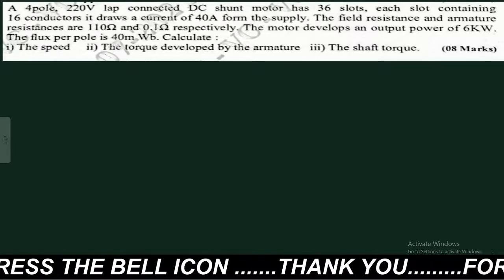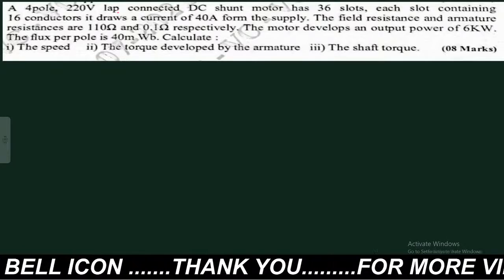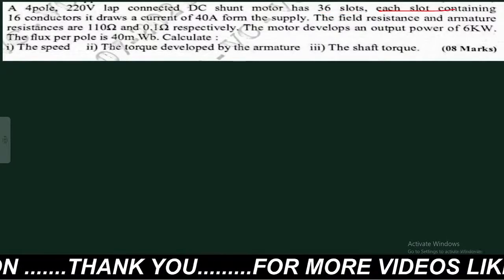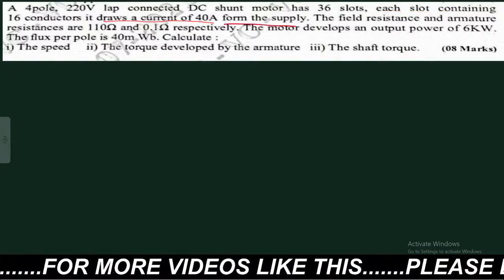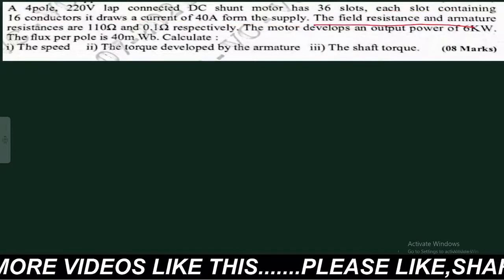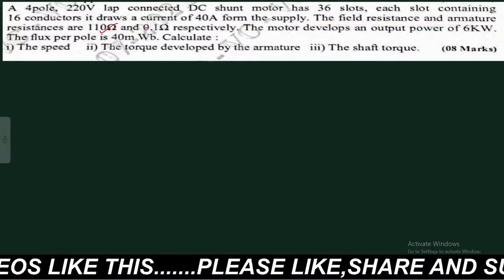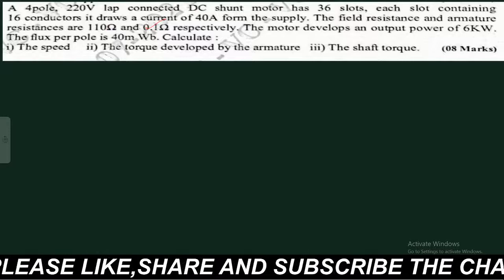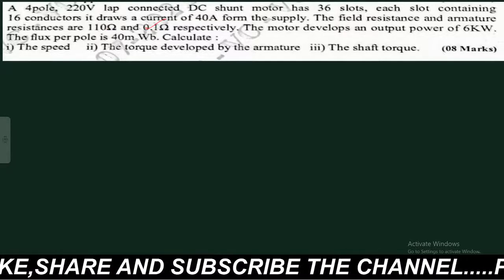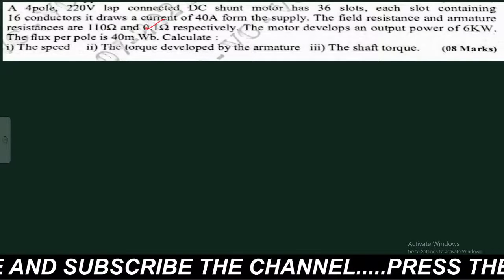A 4 pole, 220 volts, lap connected DC shunt motor has 36 slots, each slot containing 16 conductors. It draws 40 amperes from the supply. The field resistance and armature resistance are 110 ohms and 0.1 ohms respectively. The motor develops an output power of 6 kilowatts.